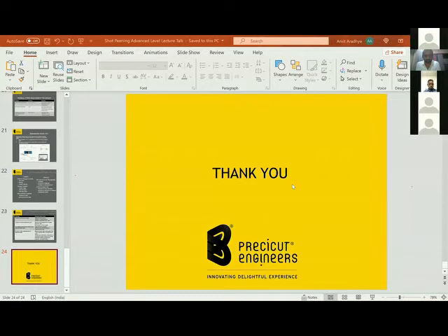Will it increase compressive strains beyond saturation? That's the question. Yes, actually, like I said earlier, it is going to increase the compressive stress because, like I said, what the designer is going to do is add some factor of safety into the process. So what happens is the stress profile, the depth of the stress and the stress profile, is going to change after the saturation point. So it is always helpful.